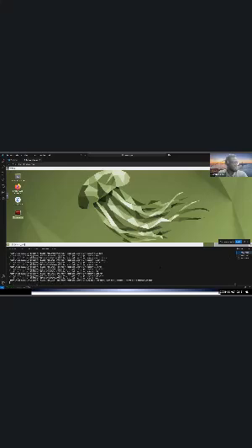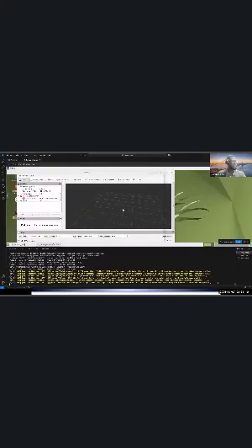I'm sure you're all excited to do that. So the next step now is to run a robot simulation. We made this package very user friendly. Once you run the Gazebo command, robot sim, it launches the Python script that launches RViz and Gazebo at the same time. So when I run it, you see now. Perfect. So you see that everything is loading.